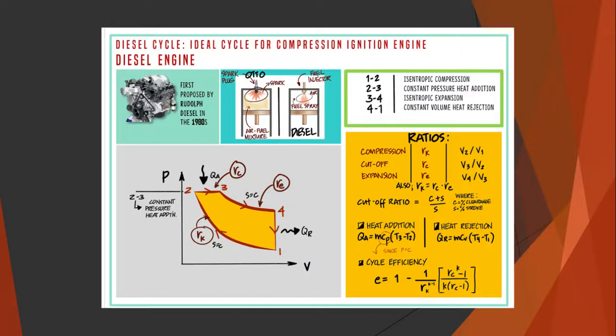The difference between the two is the simplification of the intake and the exhaust strokes in the ideal cycle. In the exhaust stroke, heat Q out is ejected into the environment. In a real engine, the gas leaves the engine and is replaced by a new mixture of air and fuel. Then in real engines, the heat addition is never isobaric.